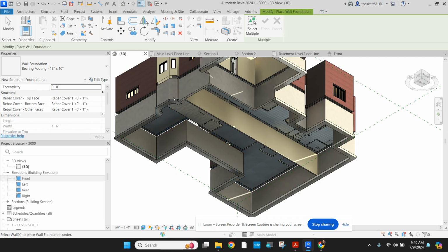Okay, now I didn't get this one right here. That little wall right there is missing one. There we go. Now, this bearing wall that goes down the middle also gets a footing because it's got to carry that weight. So make sure you get that interior wall in there. All right, that's our foundation walls and our footings. Super easy, super fast. And go and get those completed. And we'll move on to the next stage.